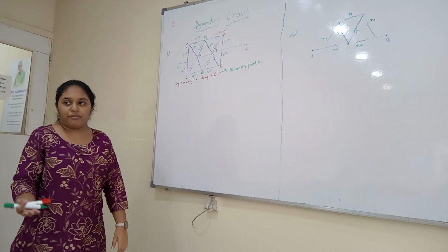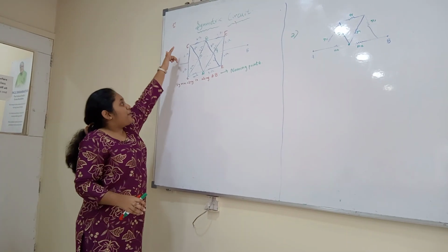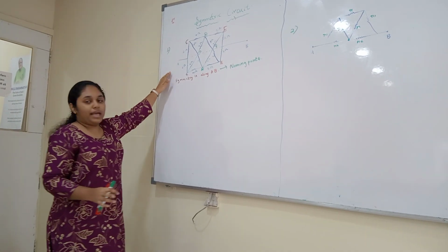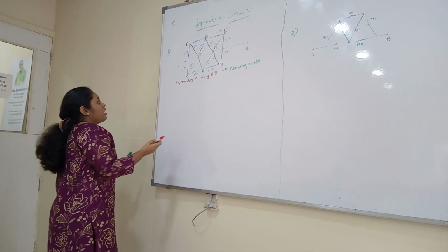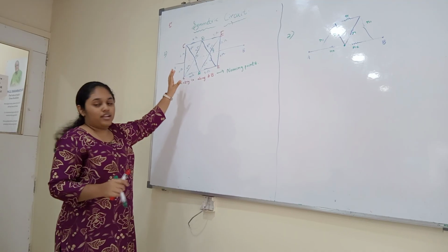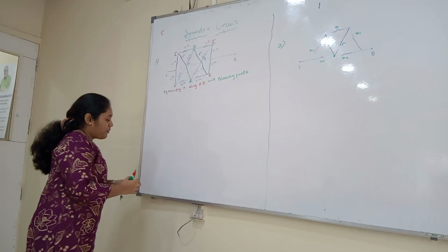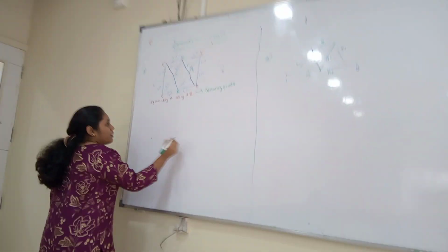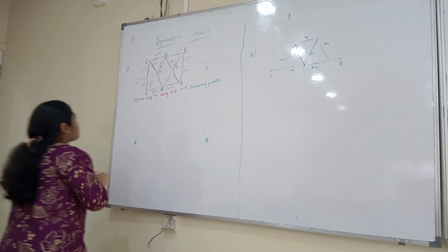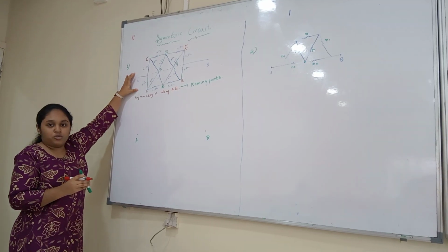Now we know naming points. If 2 resistors are between the same points, then those are in parallel, so we can apply the parallel rule. Let's redraw this circuit and apply the parallel circuit solving concept. First we will make 2 points, A and B. So AC in parallel becomes 1 ohm.